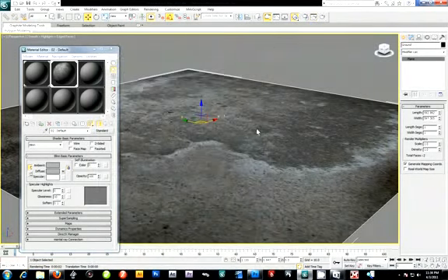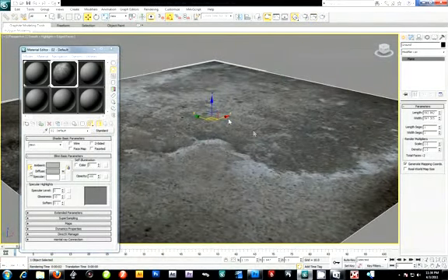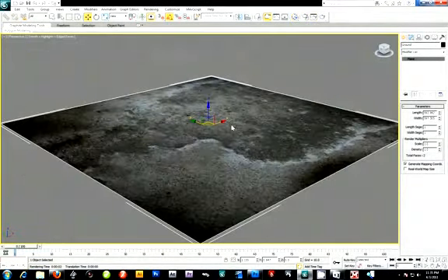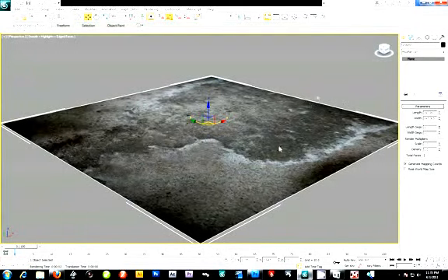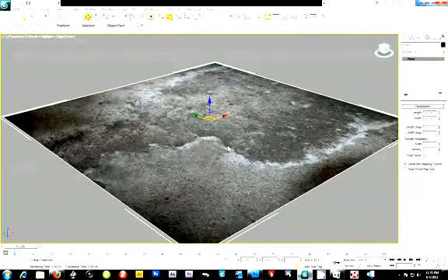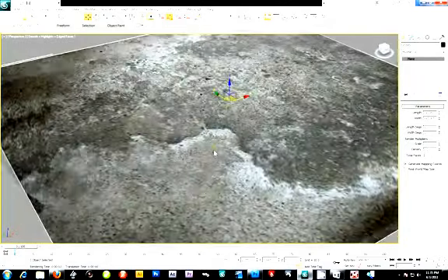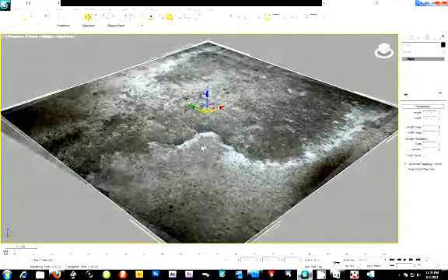Alright, but I'm going to explain another tool now. I'm going to click on my object here, and once a texture is laid down, it doesn't mean that's the right way to do it. Of course you can just drop textures on objects, and usually simple objects like planes and boxes will work out fine, but you always want to UVW map it.